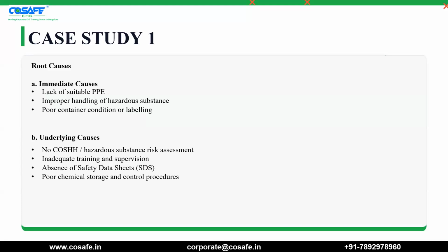When your work separates from the routine work, like in an IT company where everyone does IT jobs on laptops, there won't be a PTW system until there is separate construction or maintenance work undertaken. In production lines, routine work does not require PTW. Only maintenance work or activity that has high hazards requires PTW.